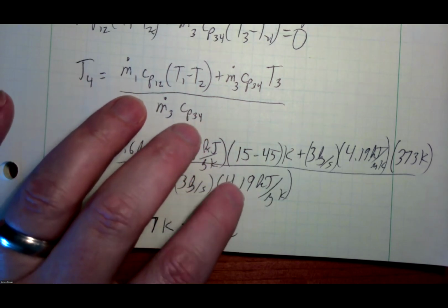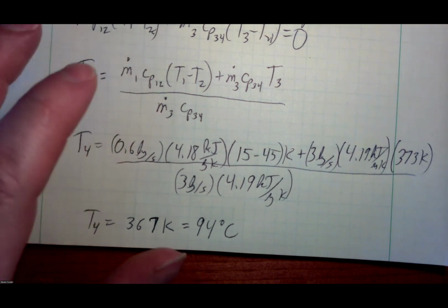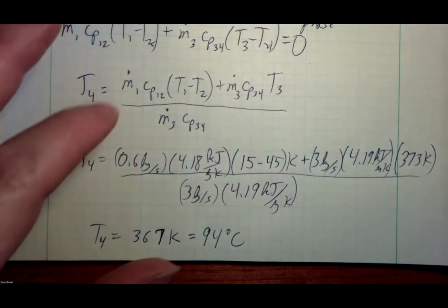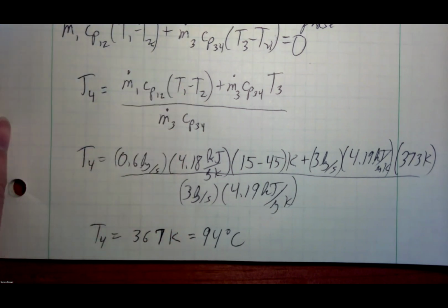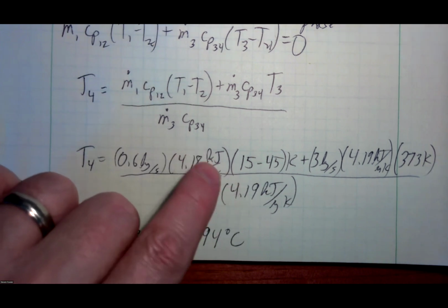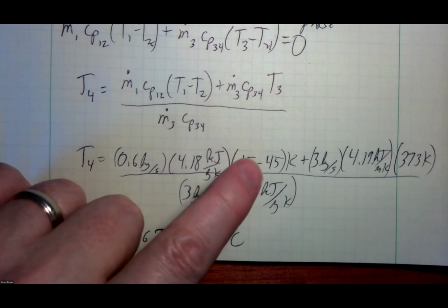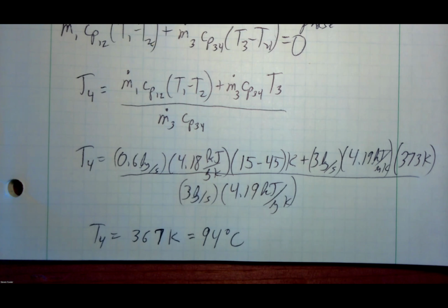If the specific heats are different, you still see that. You can see mathematically the balance. So if I've got, say, oil, like a solar powered hot water heater, where I've got some kind of an oily substance with a different specific heat, using that to heat up hot water in a hot water tank, a wonderful design. There are systems out there that do this. It's a very effective, cost-effective way of doing it. The control systems get to become a little expensive to replace, but that's another story. But that's just a situation where I've got different specific heats here and here. But if it's the same specific heat, if I've got 5 times more mass in the hot stream, I would expect 1/5 of the temperature in the cold stream.